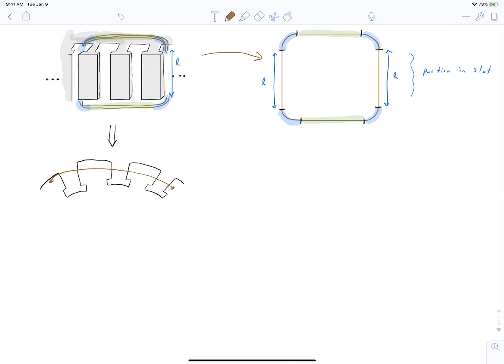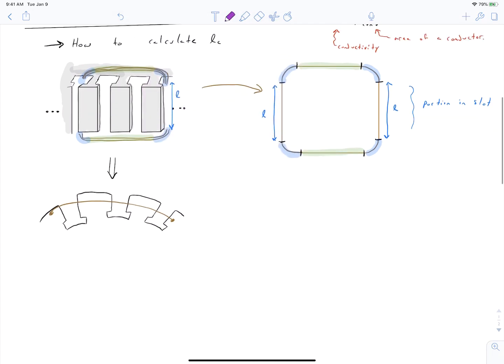Okay, so I've sketched a 2D view looking down at our coil from up above. So we've got our 3D view here, and we're staring down, and this is what we would see down here. And what we're trying to identify from this diagram is this green swath. We're going to divide it up as the region of our coil after the coil has bent around to travel circumferentially. So we're specifically sectioning off this area, and we're going to mark it as this length right here. And we're going to express this in terms of our slot pitch.